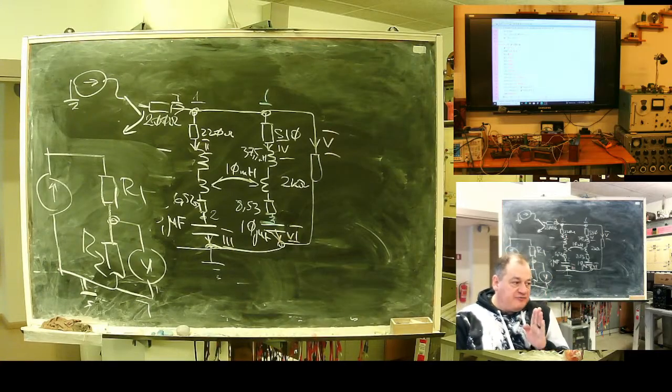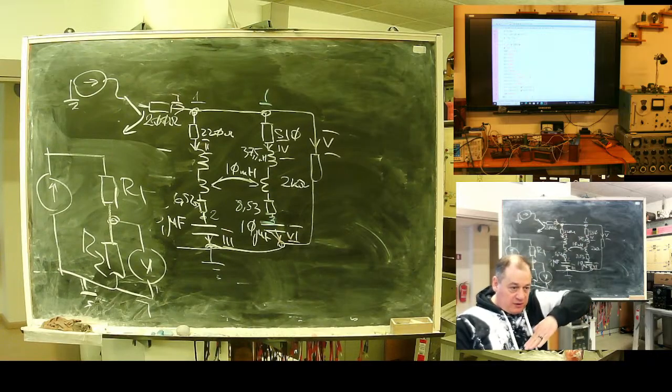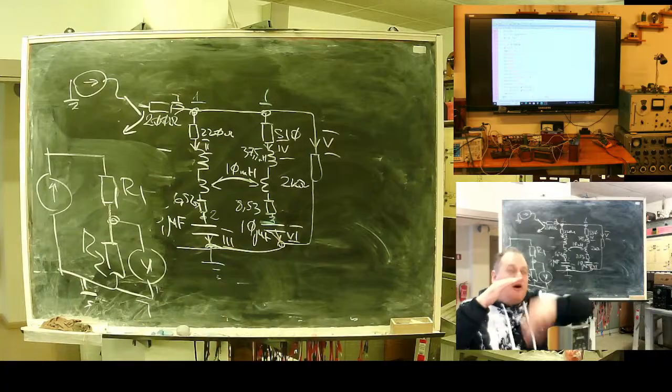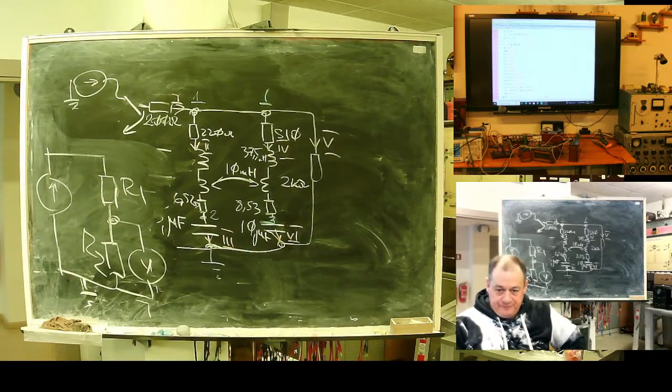Before and after. When I calculate energy stored in capacitors and coil, I need schematics before switch is opened. When I calculate transient itself, I need schematics after switch is opened.